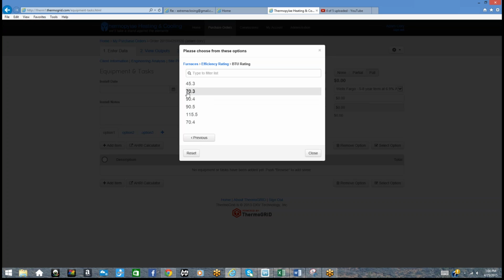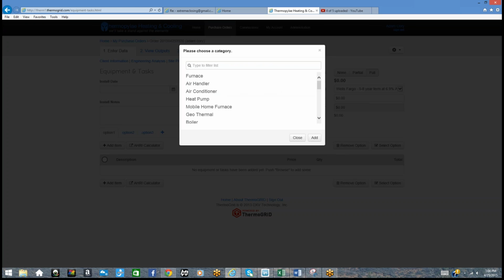Then we can pick the size of the system. Let's say it's 70,000 BTU with a 3-ton blower, and then upflow or downflow, and then there are 2 different brands available. So that's the order that this interview process is going. Once you push add, you can do one of 2 things. I can push add again, and it's going to add in this furnace with all the tagged components. Or I could go back and hit the reset button and select another item, and it will add all of the components that I've added in.